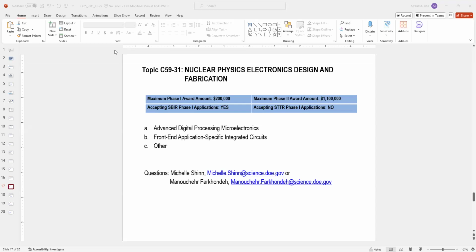We're looking at digitizers. The digitizers sit away from the instrument. They're not in the radiation environment. For our next generation, what we're seeing the community want are digitizers that could do triggered operation, the conventional way, at higher sampling resolution than what we're getting now. The effective number of bits needs to be 14, so with bits on either side, you really need a 16-bit digitizer at sampling rates greater than 4 gigahertz.